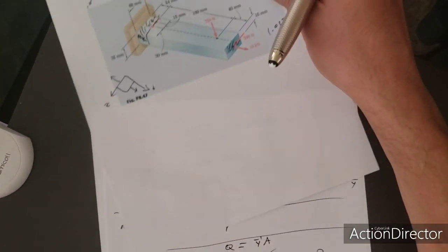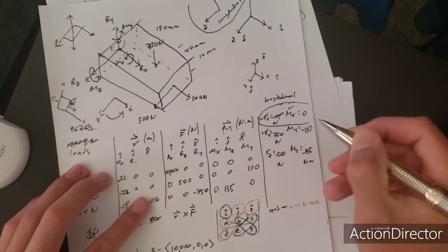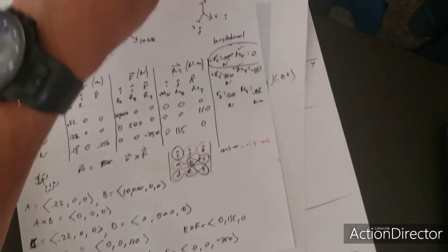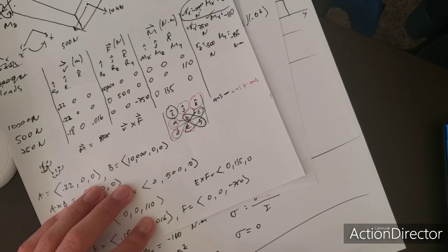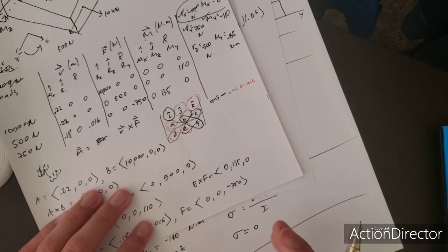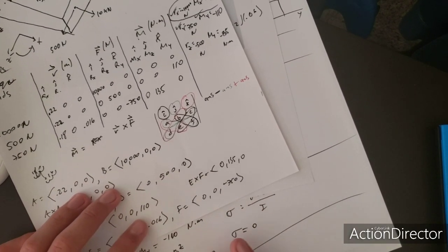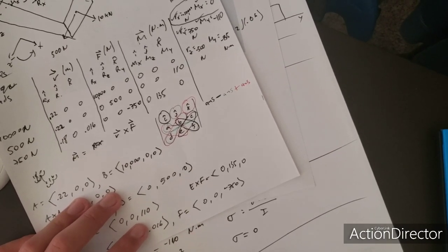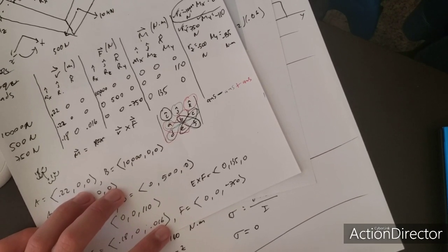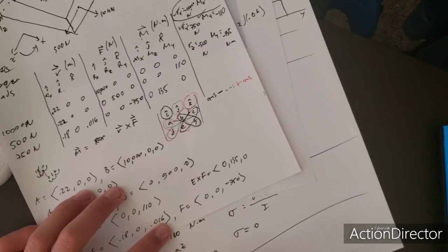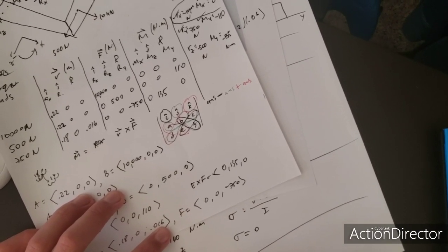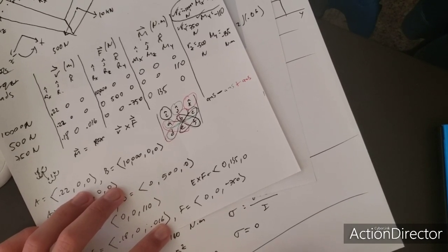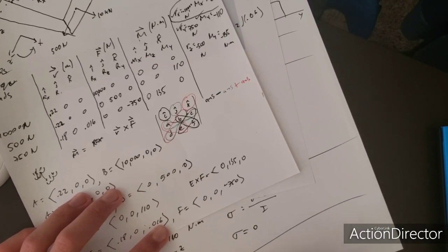The next one, we're done with that. And y, RZ. Let's look at RZ. Once again, you have a lateral direction, so you're going to have a transverse shearing stress here. What is the formula? Tau equals VQ over IT.